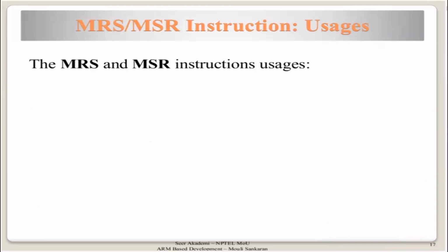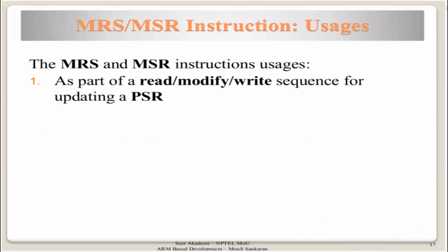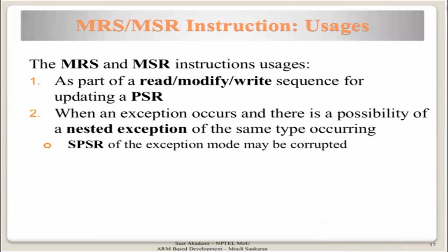So what are the usages? As a part of read, modify, write: read it, modify it, and write back. The PSR could be a CPSR or an SPSR. One more thing you should remember, and I will explain it in a little bit later: when you are changing the exception mode, it could land into multiple exceptions happening, where one exception calls the same exception again inside. In those kinds of situations, you may have to save it into the stack.